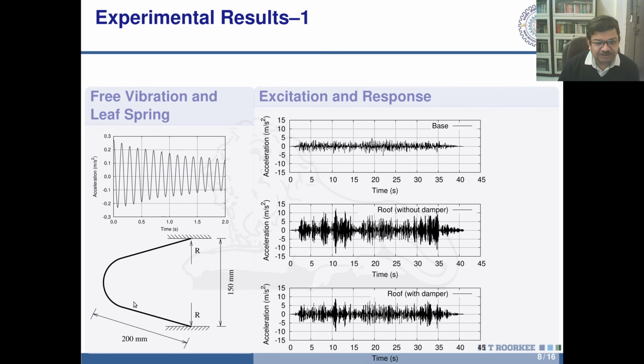And this is the typical geometry of that leaf spring that we fashioned. Essentially just sheet metal cut and bent into this kind of tongue shape, and then given heat treatment, oil quenching, to generate the elasticity that can develop the reaction at the anchor reaction blocks. The length and this opening can be calculated as per requirement.